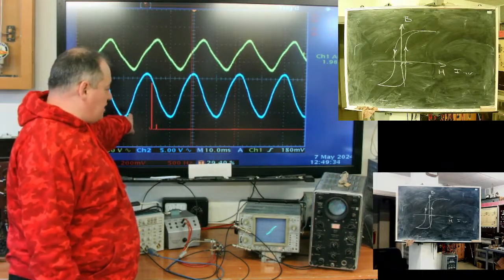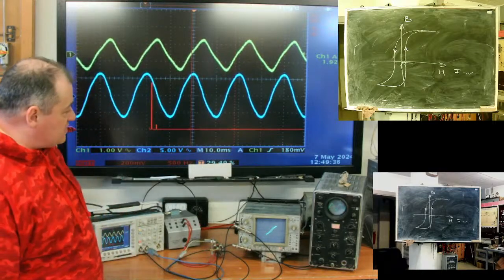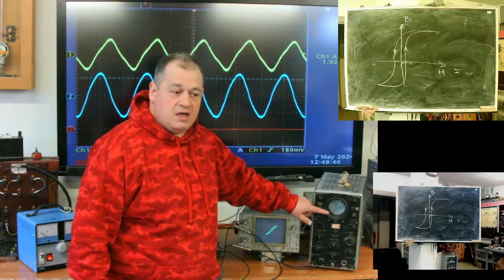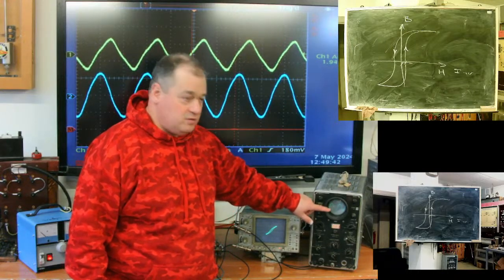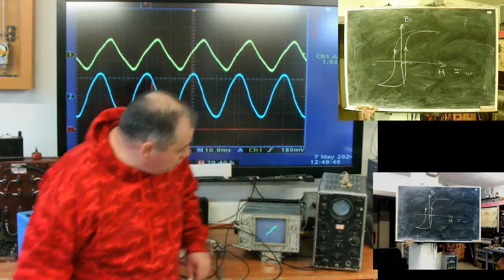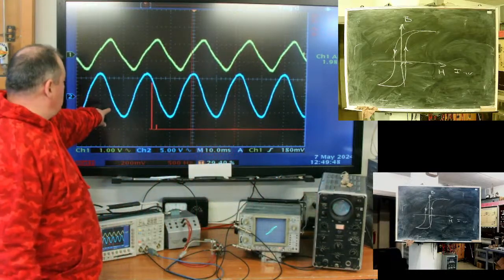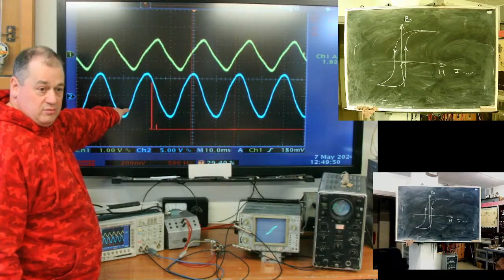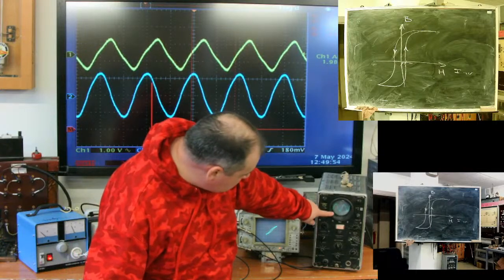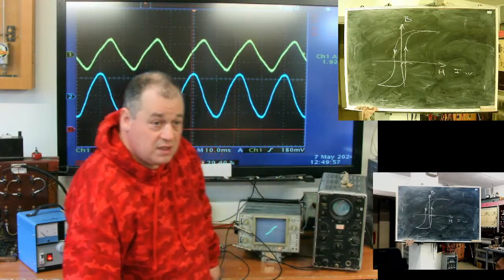This one is secondary voltage. Primary voltage is near sine. Here on the small scope, it's induction or flux. It's a flux channel. What do we see? Voltage near sine. Oh, it's harmonic, yeah? And what about flux? Also looks harmonic, yeah?